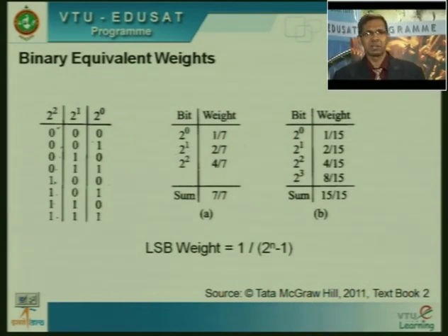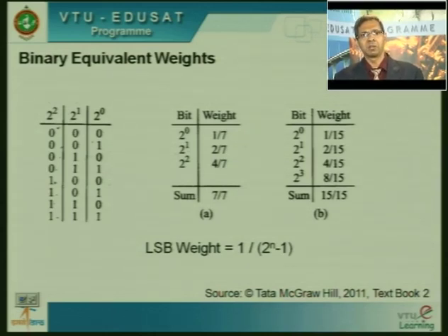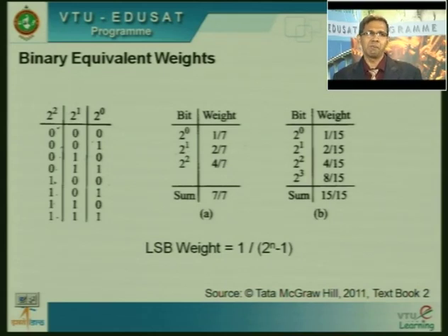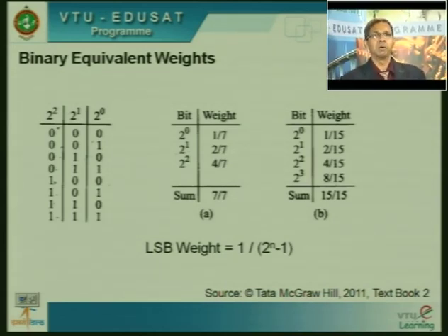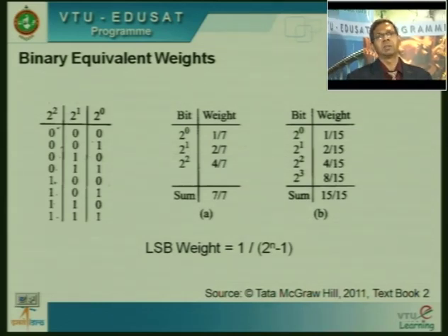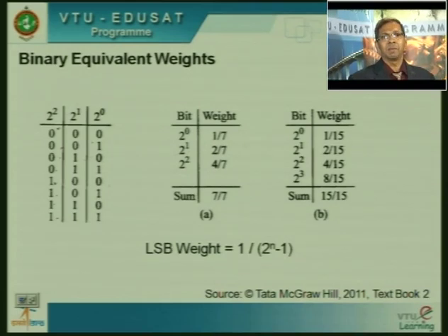We are taking 7 volts just for the ease of convenience, so we can discuss it very easily. So if you make 000 as 0 volts and 111 as 7 volts, now the question comes, what would 001 represent? What is 001 now? 001 is nothing but 1 LSB.